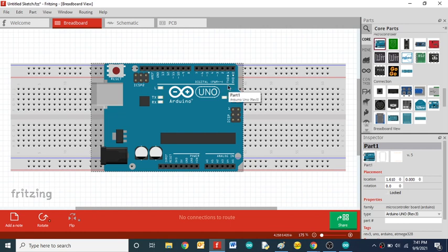If you want to use these pins as UART, you have to initialize the UART communication by providing a specific baud rate. By default these pins act as GPIOs, general purpose input output, meant only for setting the pin as input or output. But now you are using pins 0 and 1 for different functionality, so you have to initialize them as UART transmitter and receiver. We have different inbuilt functions for doing that.